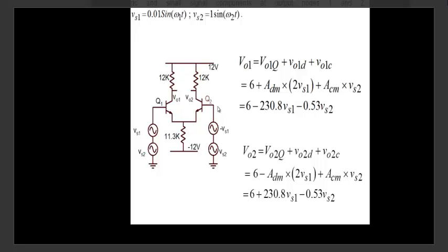All right, so similarly, suppose I say, what is the net value of current flowing through this particular resistor? It would have a bias current, right? Will there be a differential current here? Because we said in differential mode, this point is 0 and this point is also 0. So there is no differential current here due to differential signal.